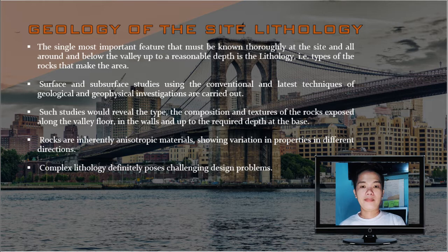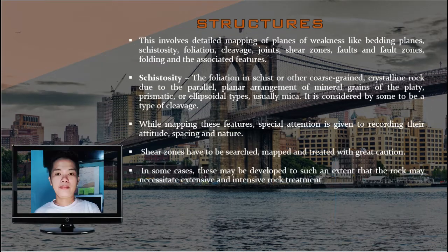Surface and subsurface studies using the conventional and latest techniques of geological and geophysical investigations are carried out. Such studies would reveal the type, the composition and textures of the rocks exposed along the valley floor, in the walls and up to the required depth at the base. Rocks are inherently anisotropic materials, showing variation in properties in different directions. Complex lithology definitely poses challenging design problems.